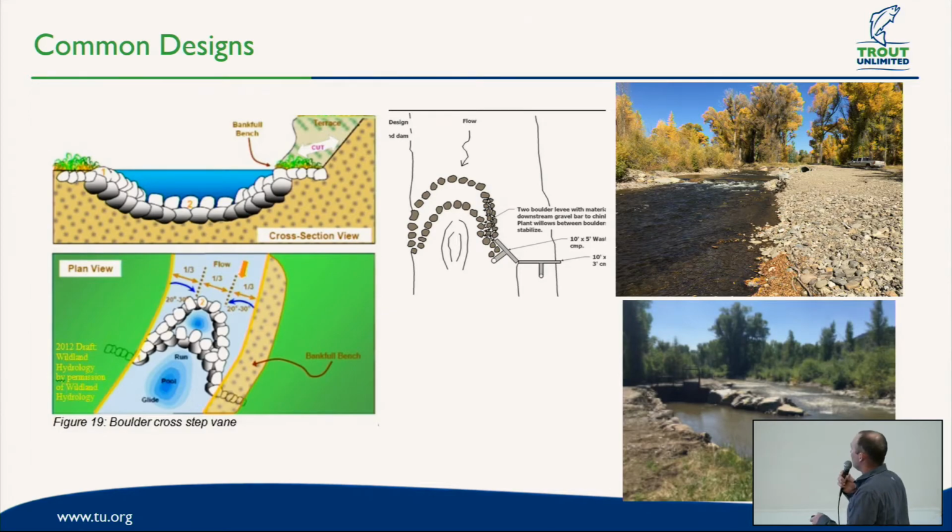Here's an example is a push-up dam on Ohio Creek. Sorry to be so shaky here, but there's a vein there and a vein here, and here's the actual head gate when that was redone. And this is the head gate, and right here is a sluice gate, just kind of a rough sketch of what's going on in this situation. And the sluice gate can be operated to kind of keep some of the fine sediment from building up in your ditch.